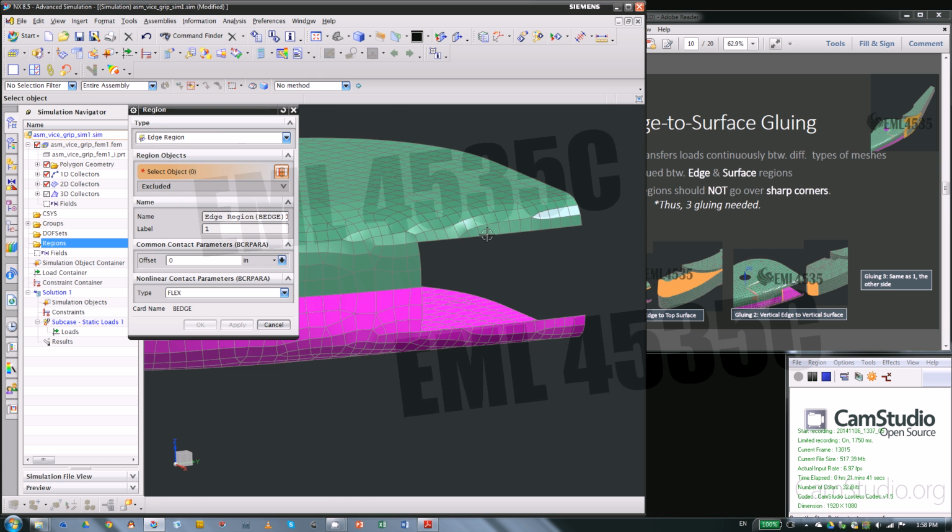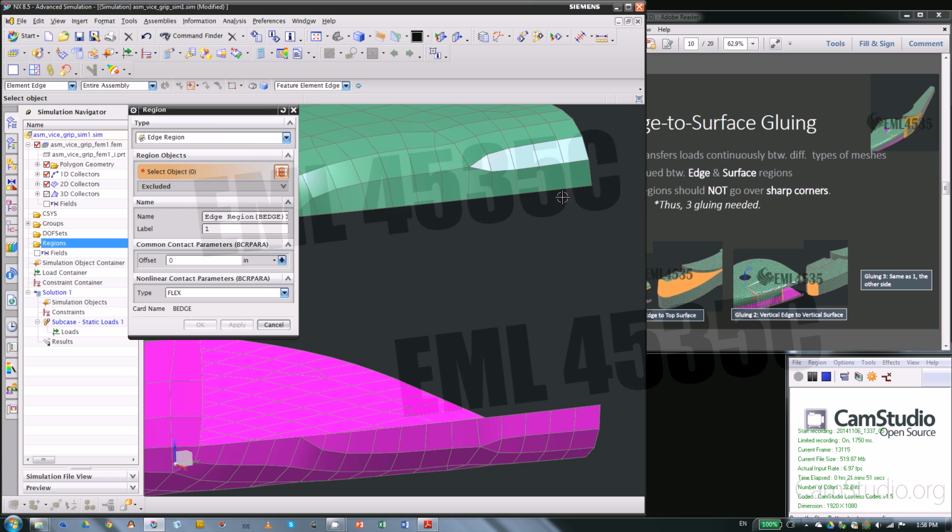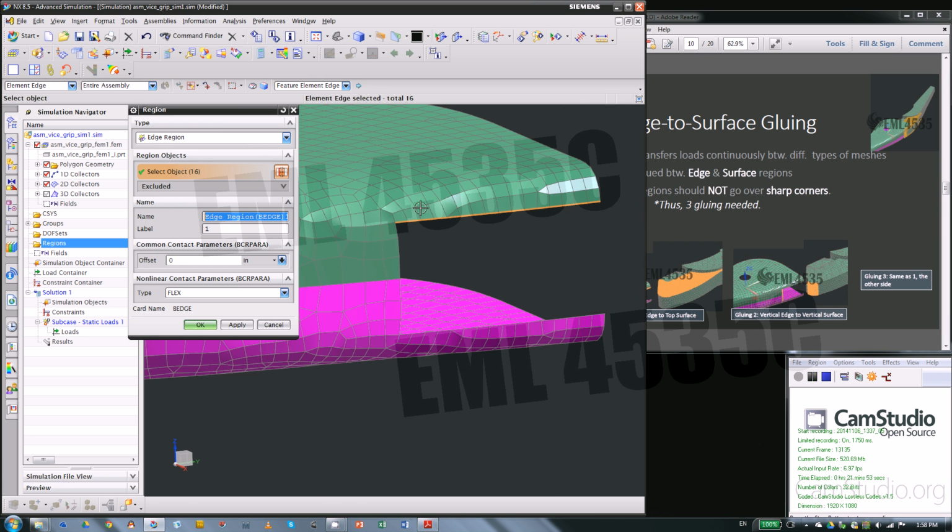So this is the top edge, and that's a long edge. We have to use some tricks. So feature element edge, then pick this edge, it'll pick the top edge, and you can rename this. Let's say that's the top, and don't have to change anything, just apply.